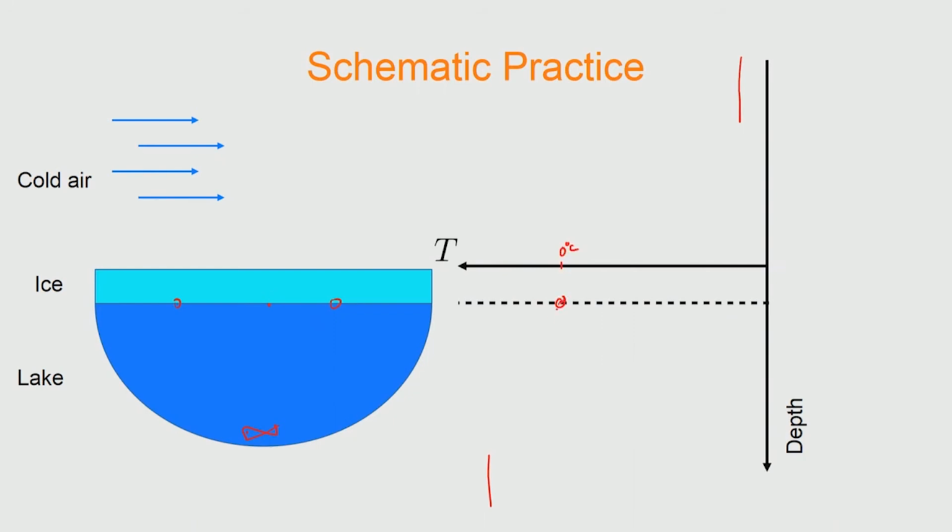So this point we know, and then the surface has to be lower than that, so you draw like that. Immediately you can draw the profile in this manner, and then you can estimate what would be the heat coming this way, and what is the heat going. The first one would be, for example, the heat transfer coefficient h inner, on the inner side, into T bulk minus T, this is 0 degrees centigrade, which is Tm.